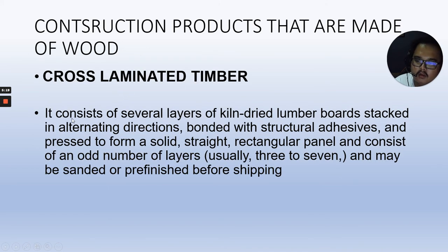Cross-laminated timber. It consists of several layers of kiln-dried lumber boards stacked in alternating directions, bonded with structural adhesives, and pressed to form a solid straight rectangular panel, and consists of an odd number of layers, usually 3 to 7, and may be sanded or pre-finished before shipping.